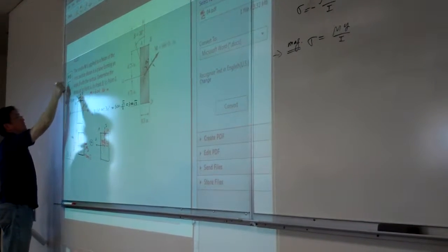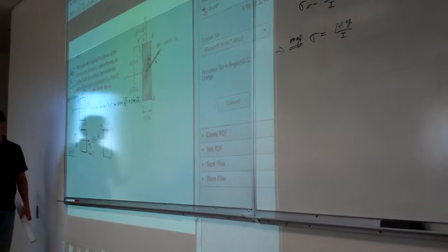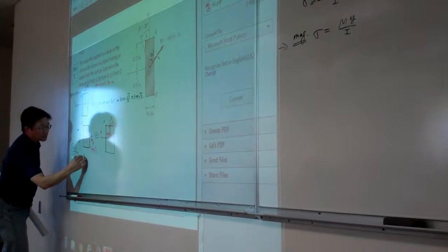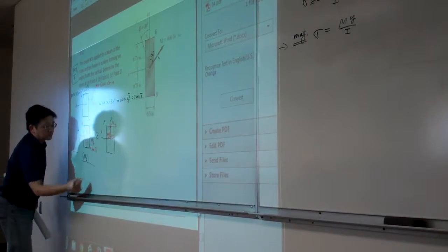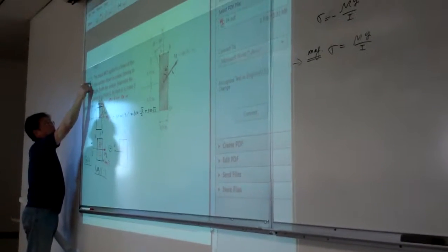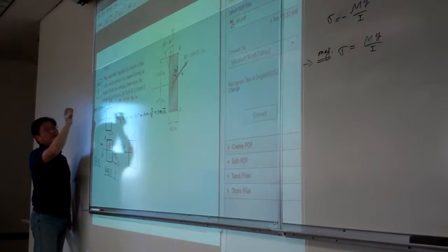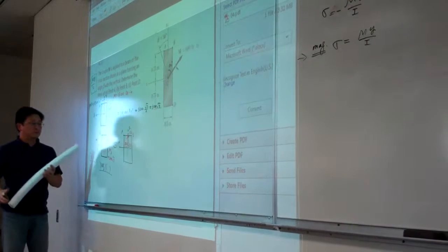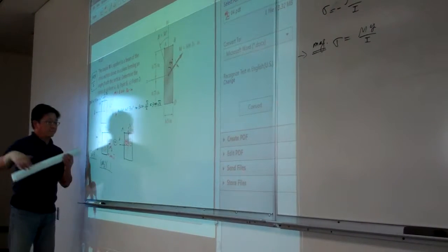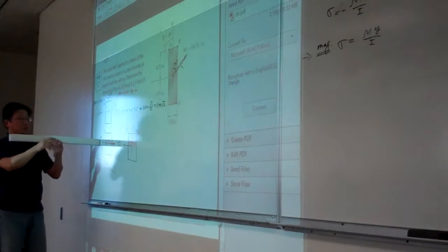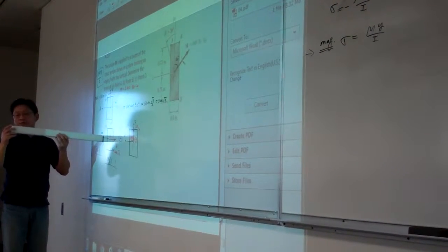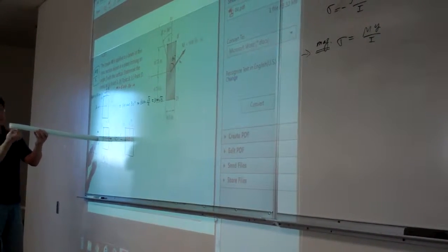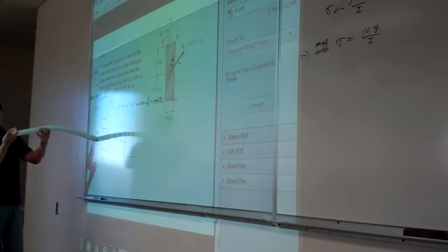So right now you can see the M, this one symbolizes the function for different things. So M is the bending. For this case, M is Mz. And what is y? y represents the distance between the point to the neutral axis. For this example, right now you can see the bending, and again, this is the beam. The Mz is about this axis. So you can see the Mz is about the bending like this axis. So that should be like this. Mz about bending about this axis, and then bending over like this.